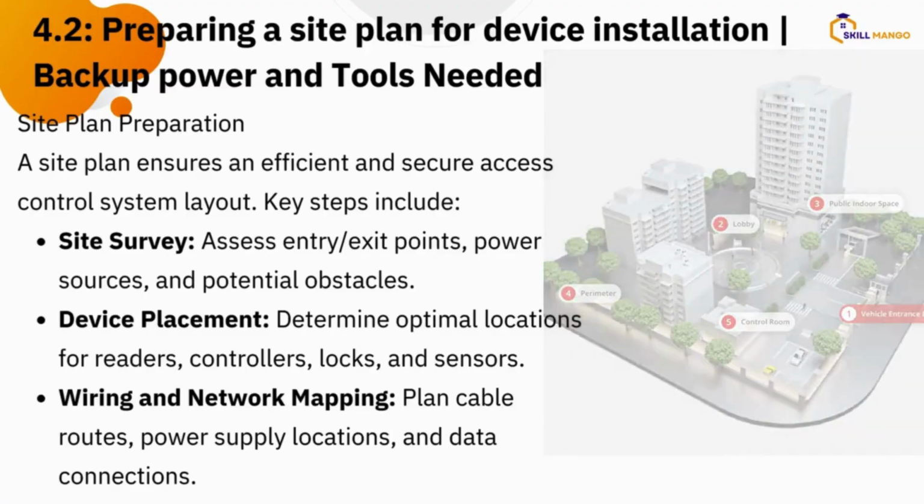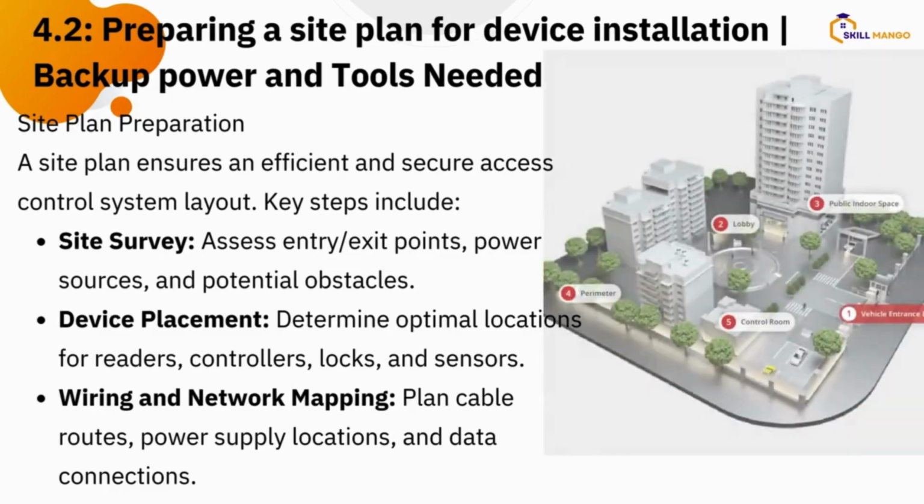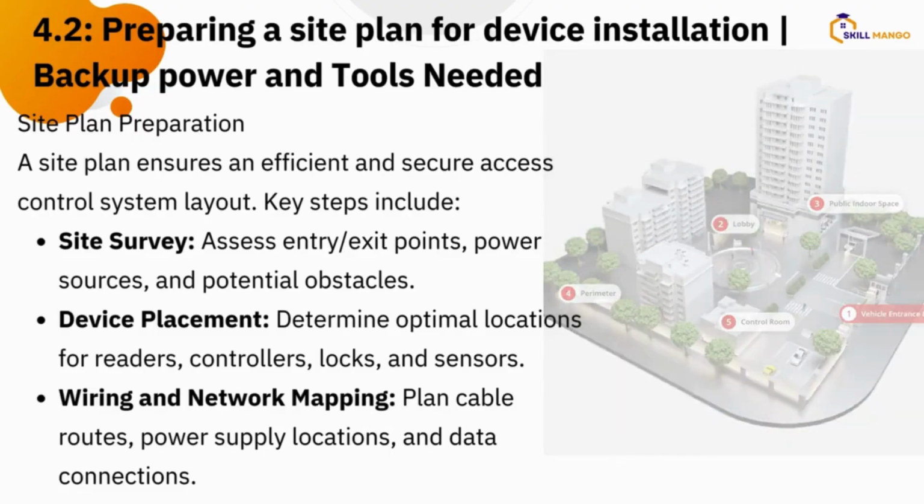for the ergonomics, okay? Then look at the wiring and network mapping. This also has to be considered because if you are doing a standalone, all the devices will be wired to the reader. So you have to be able to drill, bring your wire, do some piping, everything comes to the reader. Then the reader gets the power supply from the backup system.